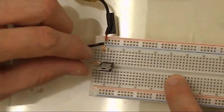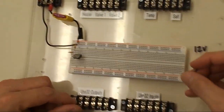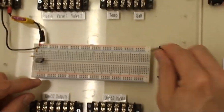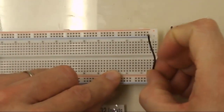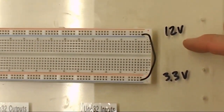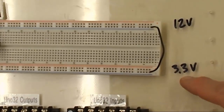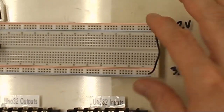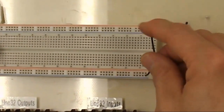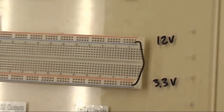One thing to point out here, let's go ahead and add one other. I have a few extra wires that you should include. So we want to connect the 12 volt ground to our 3 volts ground coming in. And so I'm jumpering it across, and this side will be used for 12 volts, and this side will be used for 3.3 volts coming off the Uno32. So we want to be careful. We don't want to jumper the 12 volt and the 3 volt together. That won't work. But we do want the grounds to be tied together, and so that's the purpose of this jumper wire right here. Now let's go back to our circuit.